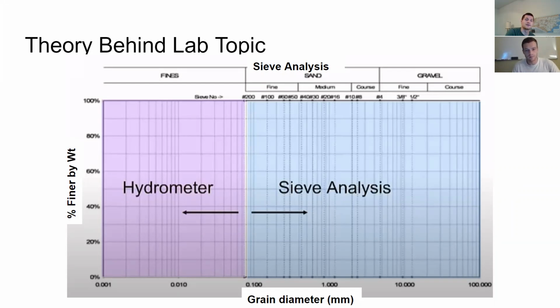graph. The hydrometer test enables you to determine the clay fraction of the soil. Although not necessary for USCS classification, it is used to better develop the grain size distribution for the finer portion of the soil.